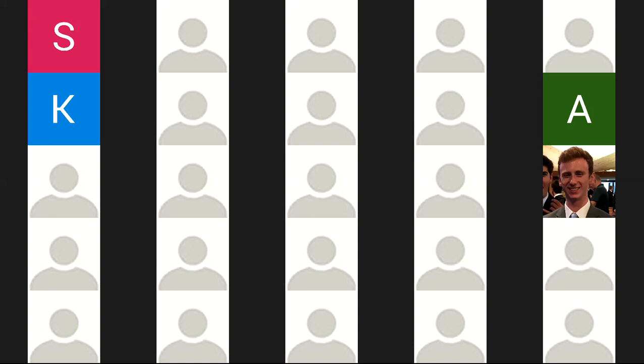In exam, though, I prefer you use 0.002. This is what I prefer, but 0.0018 is okay as well. So this is the minimum reinforcement for the slab.